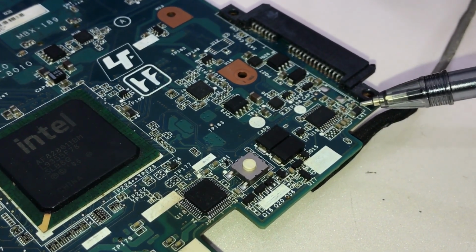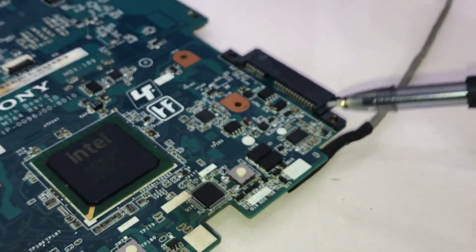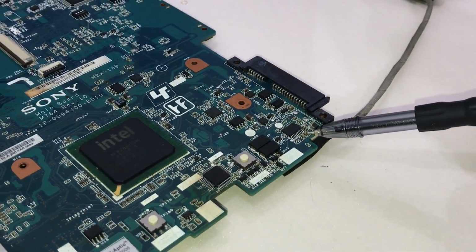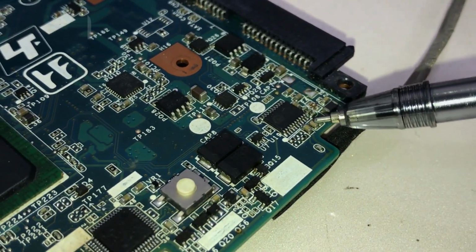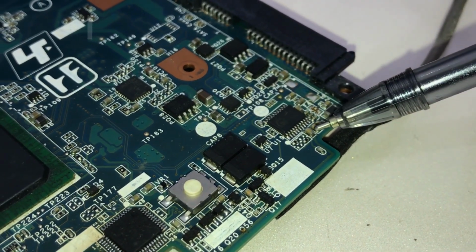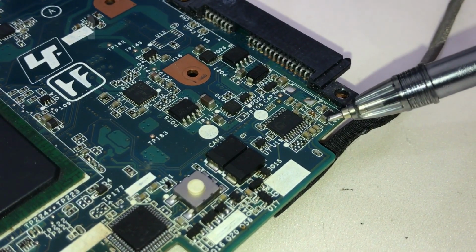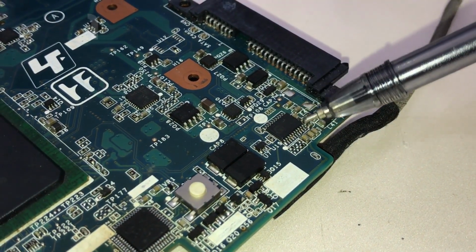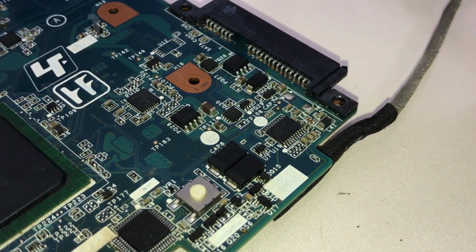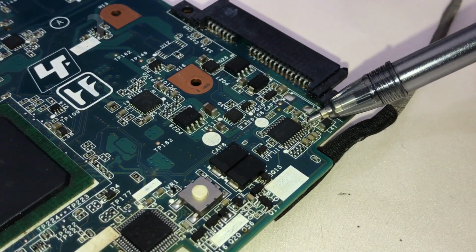I made equipment for testing the amplifier, which I'm going to show you. There is a signal injector, so you need to apply a signal to the amplifier input. Then you hear a beep from the speaker, which you can test by applying audio noise with my hand amplifier to the speaker. And I'm going to show this practically. Once you hear a weird, slightly high sound from the speaker, there would be no need to test the amplifier IC power.